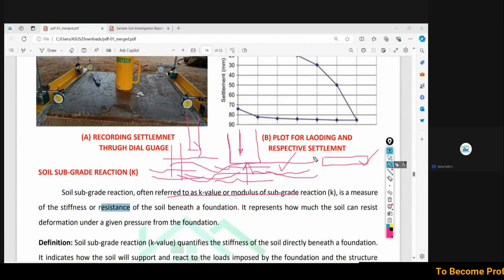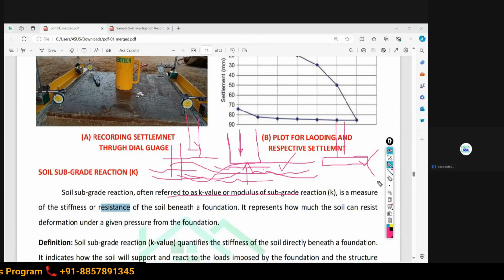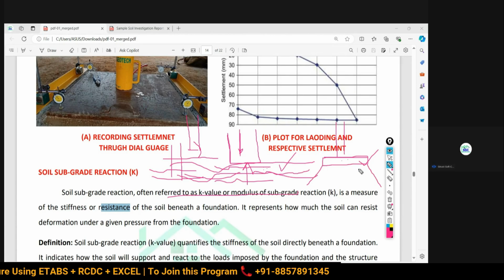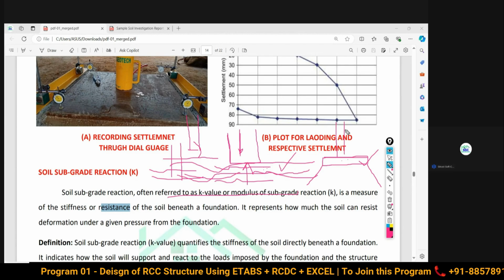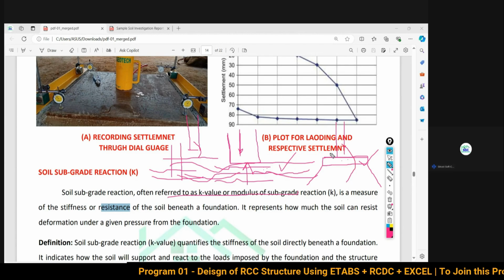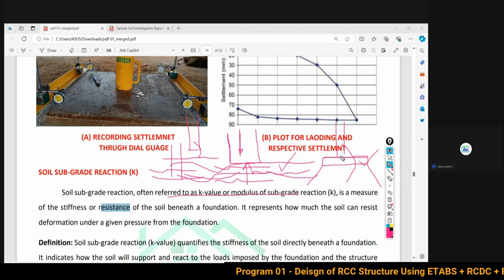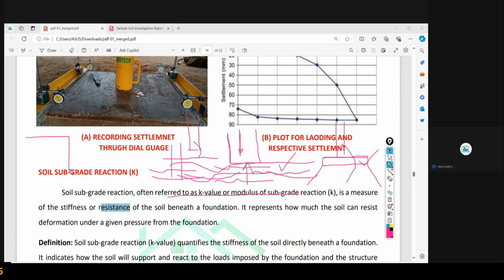मैंने कल भी कहा आप लोगों को, foundation is just a platform to give to the column. Ultimately the load is going to be transferred to the soil. ओके, ऐसा भी नहीं है कि हम लोगों ने फाउंडेशन दिया तो अब लोड सॉइल के ऊपर ट्रांसफर नहीं होने वाला है. That is also not the case. अल्टीमेटली लोड तो सॉइल के ऊपर जाने ही वाला है. So why are you going to put your foundation? So actually we are distributing the load over a wide area.